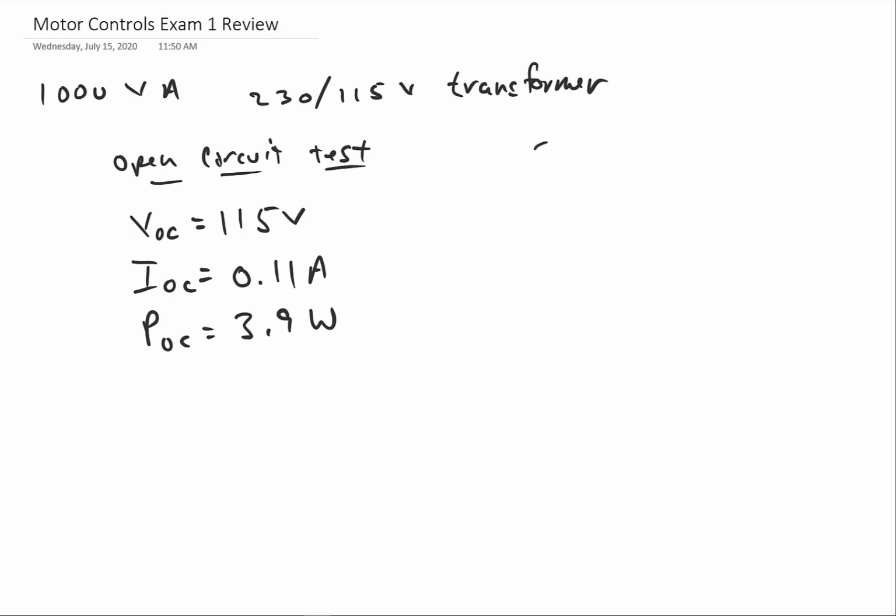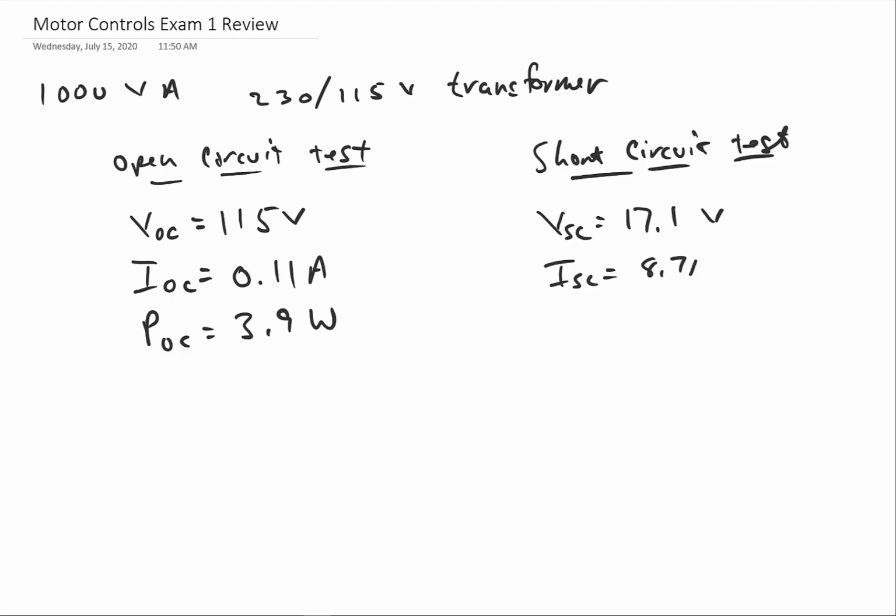For the short circuit test, we had a short circuit voltage of 17.1 volts, a short circuit current of 8.7 amps, and a power of 38.1 watts.